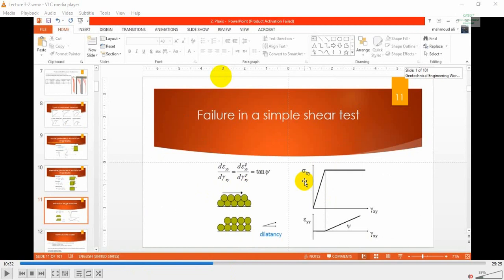After finishing the linear elastic model, we are going to talk about another model called the Mohr-Coulomb model. The Mohr-Coulomb model is an elastic perfectly plastic model. But before we start speaking about this model, we need to clarify an additional parameter that we will need to use in our Plaxis simulation. This parameter is called the dilation angle, or psi.